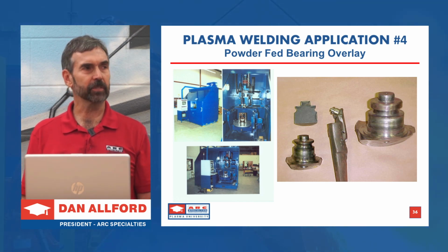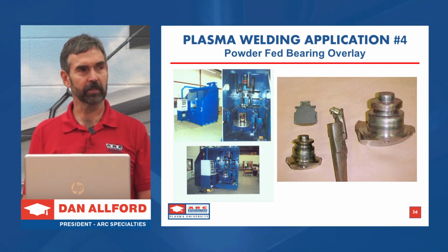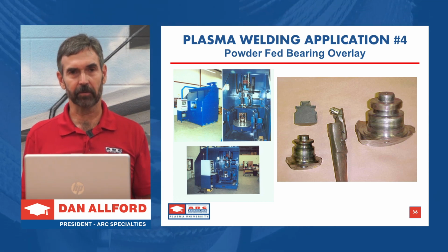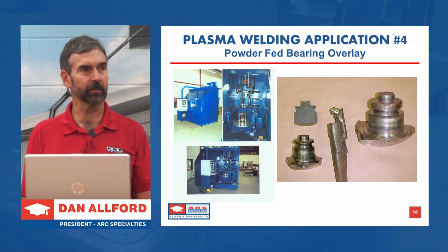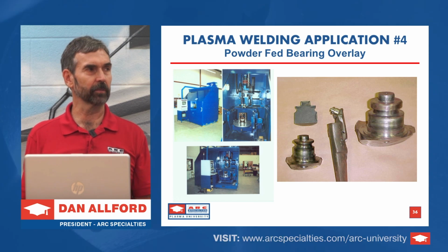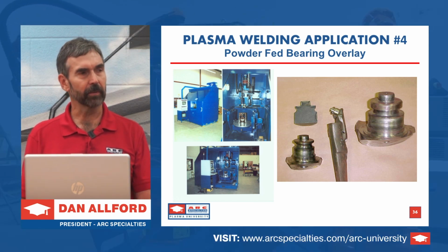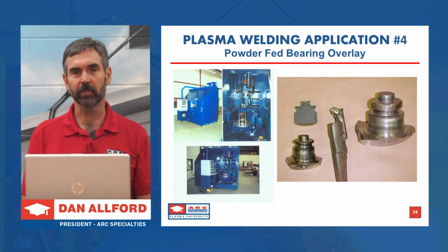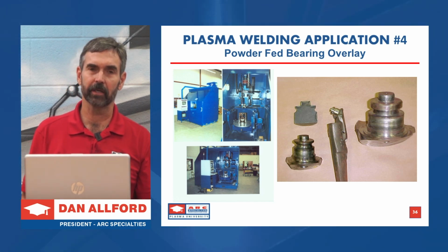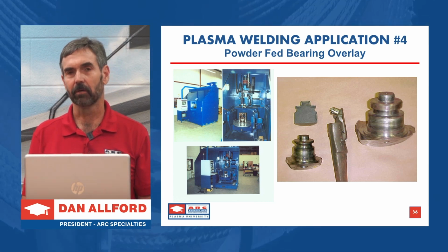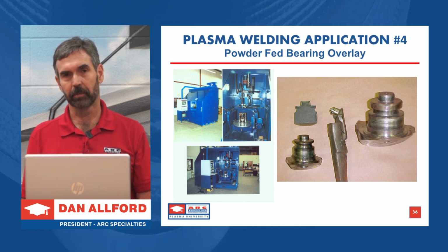Why? Because it's a great way to put down filler material, and you can use the powdered filler material. So we're running a Stellite 190, which is a high carbon Stellite 1 alloy. This is a CNC based system. And what's amazing about plasma is you can get near net shape. We were hitting plus or minus 7 thousandths of an inch on finished bead dimensions.